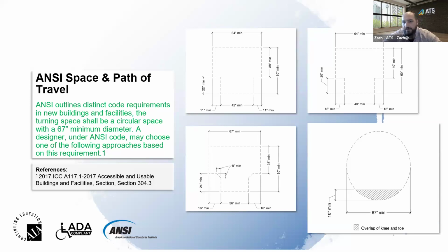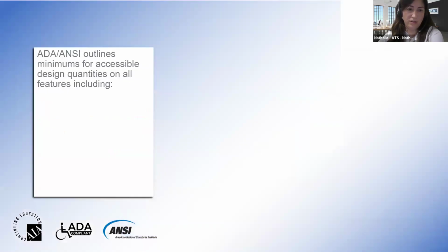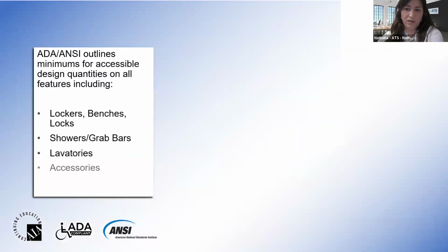And every barrier-free water closet stall or enclosure in a washroom shall have a clear turning space within the stall and in front of the stall of 1,500 millimeters. So a slight difference from each code, but always good to know.